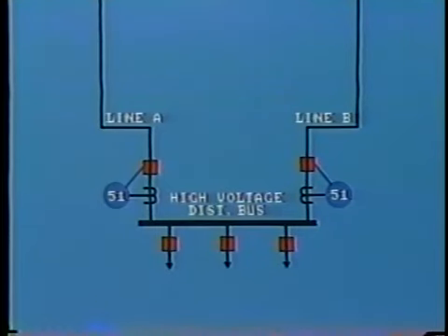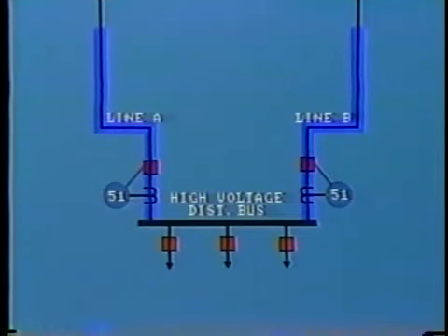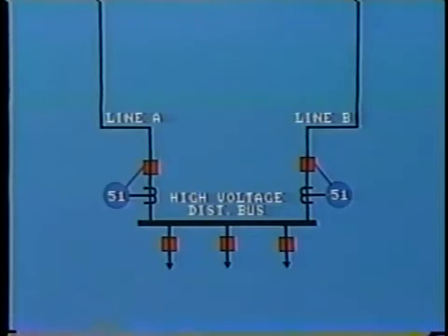This example shows the high-voltage bus in a distribution substation. It is fed from sub-transmission lines, which are part of a continuous loop. In this arrangement, current may flow in or out of either sub-transmission line, depending upon conditions or system configuration in other parts of the loop.